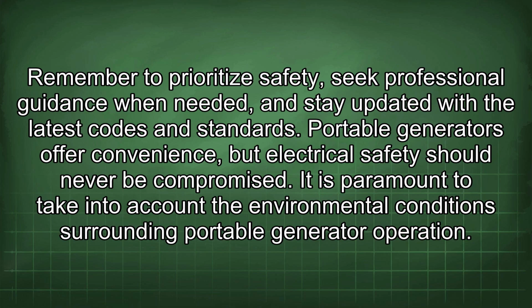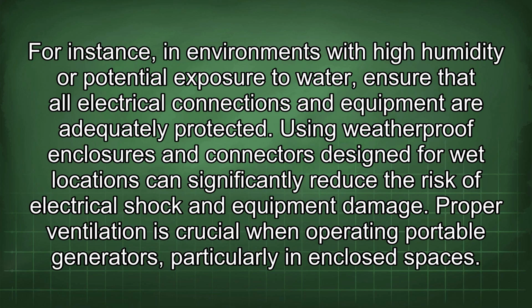Portable generators offer convenience, but electrical safety should never be compromised. It is paramount to take into account the environmental conditions surrounding portable generator operation. For instance, in environments with high humidity or potential exposure to water, ensure that all electrical connections and equipment are adequately protected. Using weatherproof enclosures and connectors designed for wet locations can significantly reduce the risk of electrical shock and equipment damage.